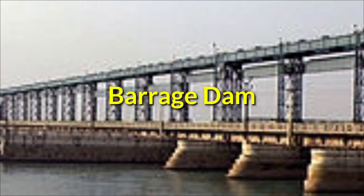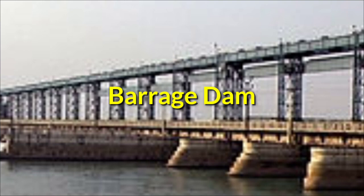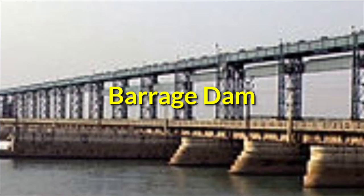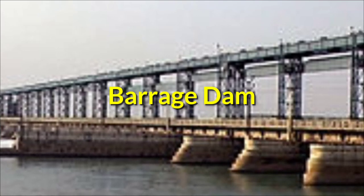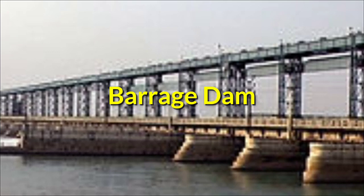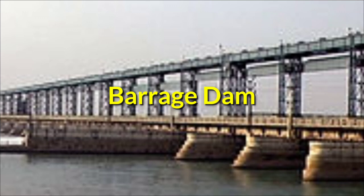Next is the barrage dam. A barrage dam is a type of low head or diversion dam which consists of a number of large gates that can be opened or closed to control the amount of water passing through it. This usually allows the structure to regulate and stabilize the river's water elevation upstream for use in irrigation or other systems.